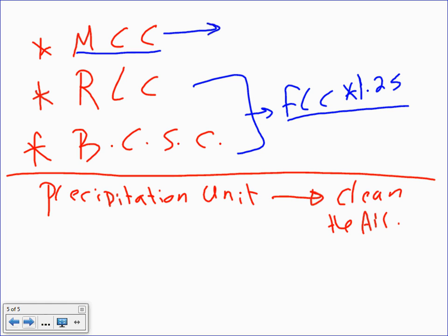As they blow the air in the unit, it charges the particles and the fumes, especially the little particles. It gives them a positive charge and pushes them. Another panel is negatively charged. So what happens if you throw a little particle with a positive charge at a filter that's negatively charged? It sticks to it, and that's how they collect them.